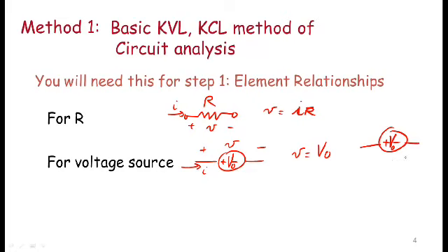However, when I take this voltage source and put it into a circuit, it's going to draw some current I, and there'll be some voltage across it. If there's a resistor, it'll be some other voltage. But if I put an ideal voltage source with the internal voltage V0 into a circuit, then the branch variable V associated with that will also be equal to V0. But in general, that doesn't have to be true.